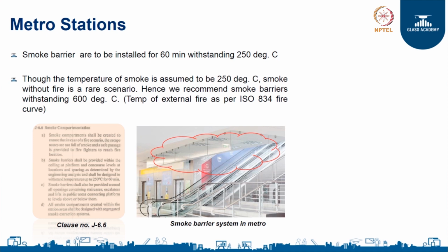The smoke barriers are always installed and tested as per the smoke barrier systems. The smoke barriers are to be installed for 60 minutes of duration, throughout which they can withstand a temperature differential of 250 degrees.